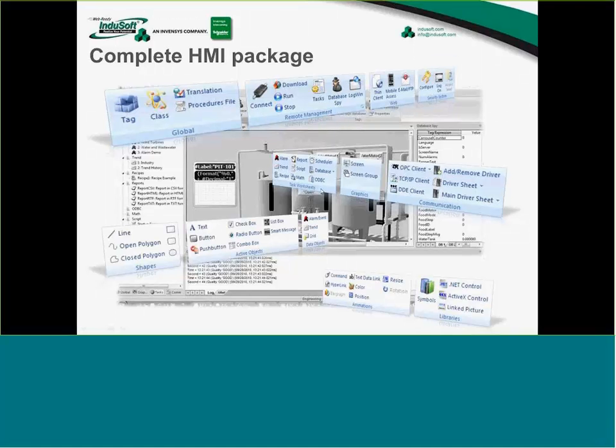We have these things called task worksheets that allow you to configure alarms, how trends and data get logged, recipes, reports, scheduling things based on time or date or a frequency, things of that nature. We also have communications, whether or not you're using the built-in drivers, one of the 240 that we have. I'll do that as part of the demo that I go through here in a minute, as well as optionally OPC clients. We've got a lot of different flavors of that, whether it's the traditional OPC DA or a little bit newer, the OPC UA type of information.